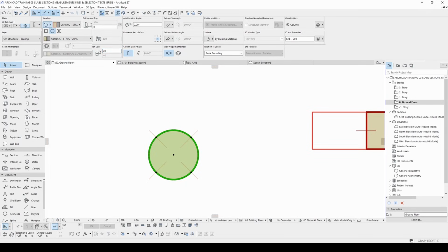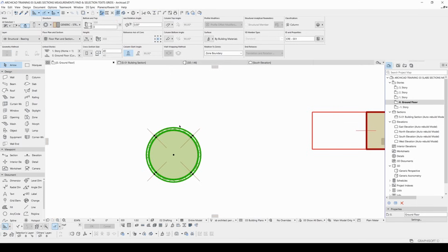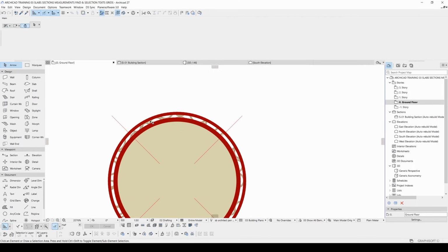And after that, I can add the veneer icon. As you can see, the veneer is 10 centimeters. You can make this 2, and you can determine your veneer as core, finish, and other. Actually, selecting finish will be more meaningful. And with this icon, you can change the building material of the veneer part. And you will see the edge will be immediately changed.